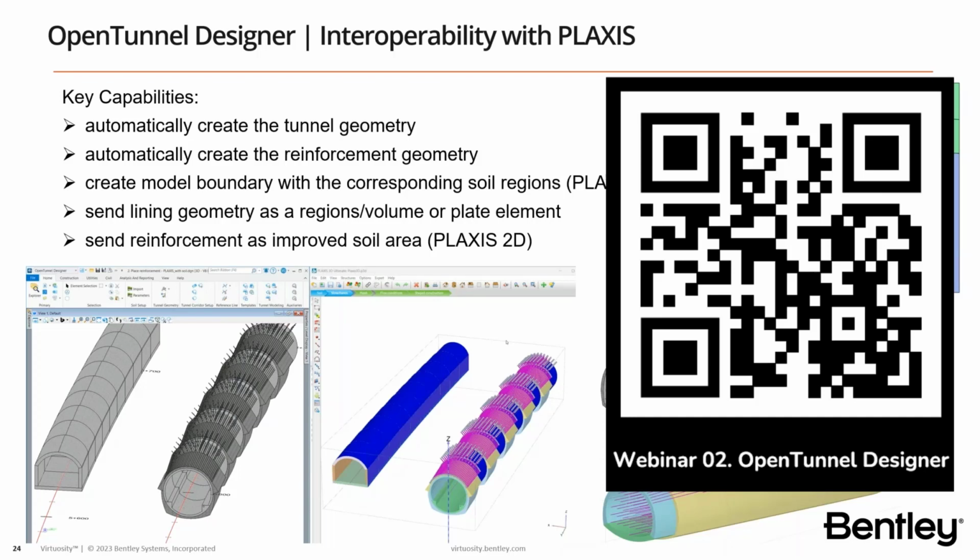And in this case, sometimes the geotechnical engineer will just quickly recreate the tunnel, but will not add all the additional information that is not needed inside Plaxis. He can also make some simplifications and assumptions so that he can have a quicker run inside Plaxis without problems.